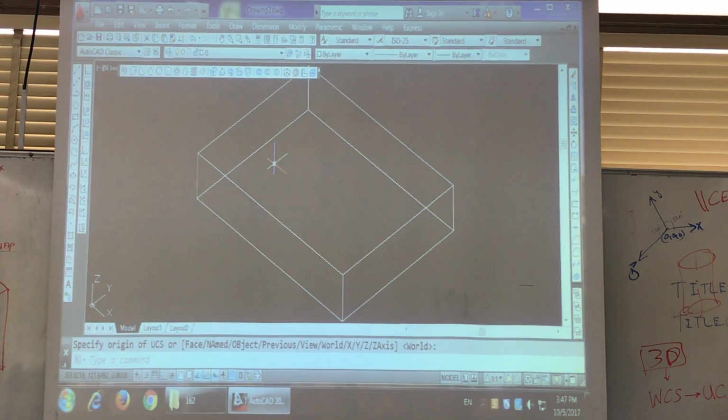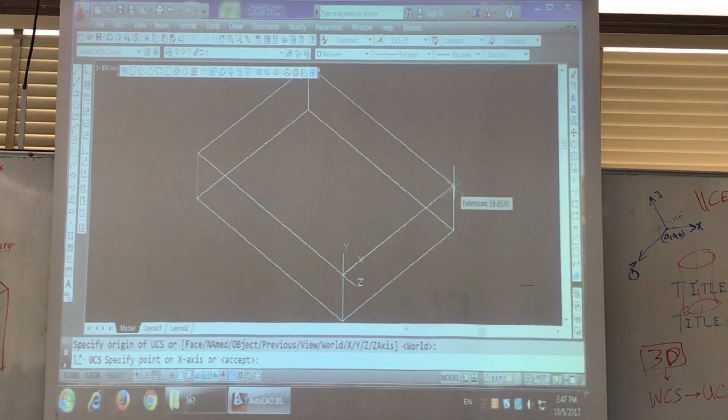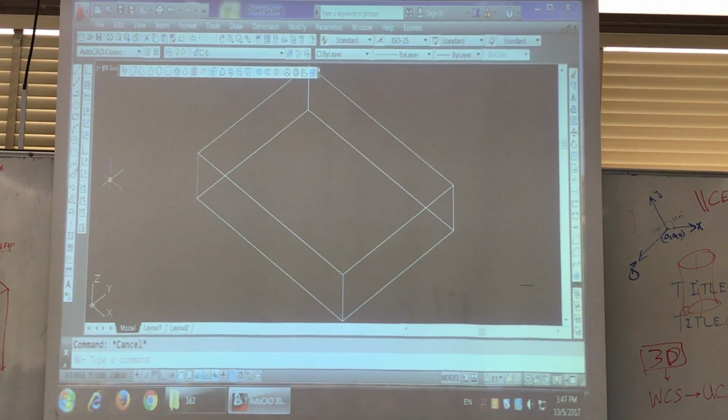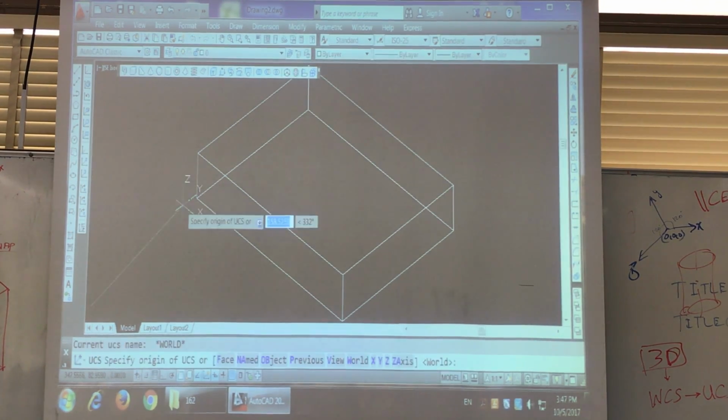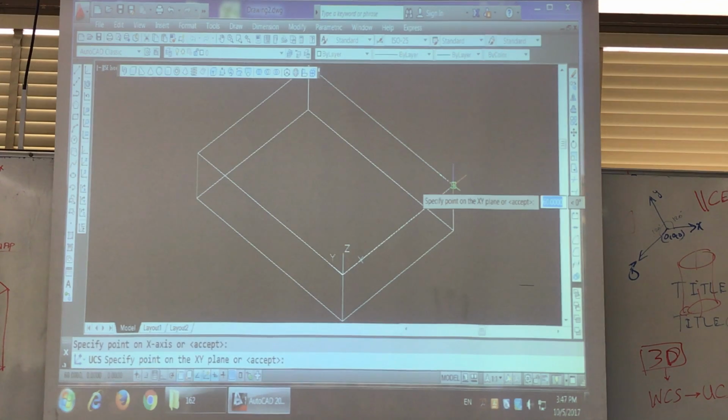So we are just writing the command, or you can select UCS from here, this one, and then say bring UCS here. I want the x-axis in this direction. So just click there, then press enter. Done, x-axis in that direction, whichever. Like that. UCS, press enter. So this is where I have brought it.